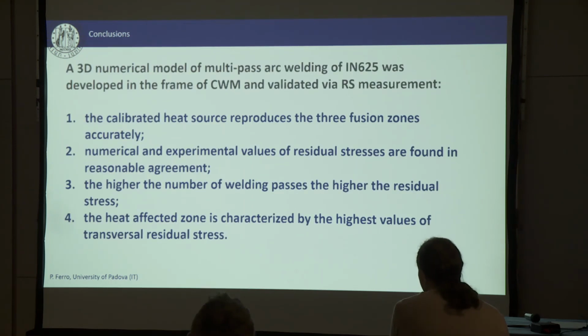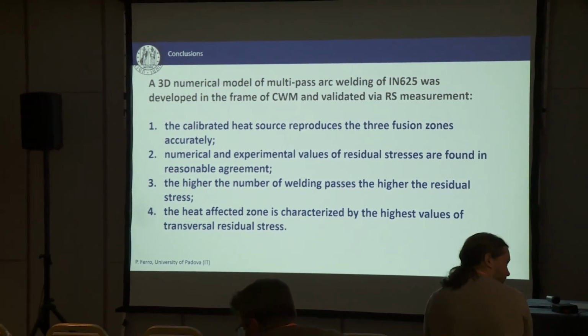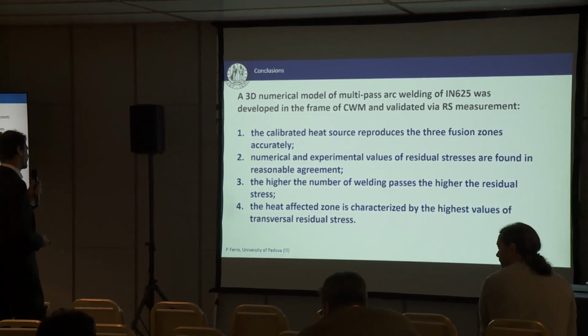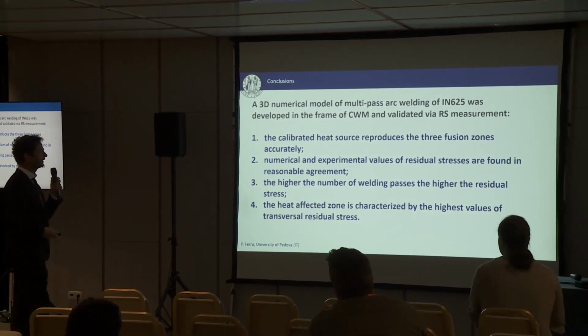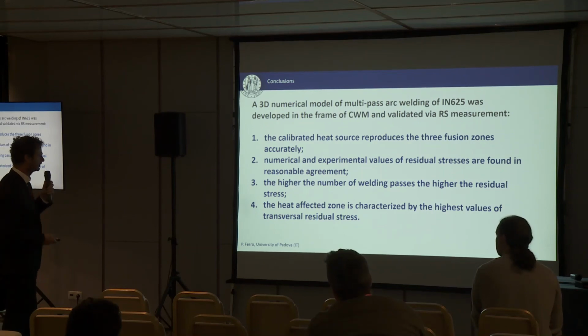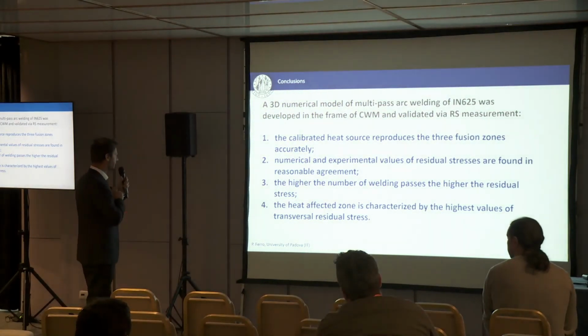So finally, for the conclusion, we developed a 3D model of the welding of IN625. We apply the computational welding mechanics approach, that is an uncoupled approach between thermal and stress analysis. Main results are that we were able to calibrate the heat source, the geometrical parameters of the heat source. Also, the model was validated by using residual stress measurements. The higher the number of welding passes, the higher the residual stresses.